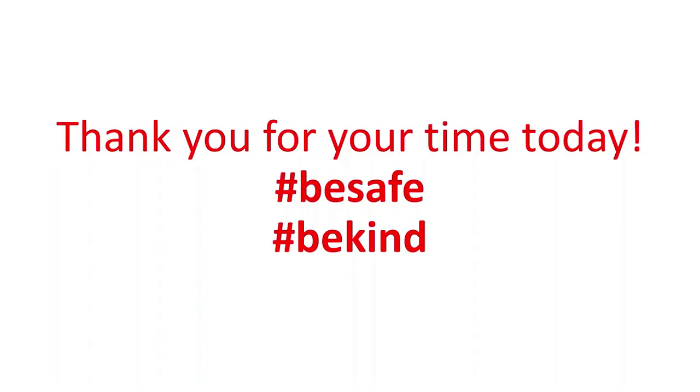When I'm 3D modeling, one of the things that you utilize in 3D modeling, they're called dumb solids or AutoCAD solids because they have no functionality. And you can use things like Boolean algebra, which is things like union, intersect, and subtract. But there's a fantastic little app in there called Trim Split. And what it allows you to do is trim and split a protrusion from a 3D object away from the main object.